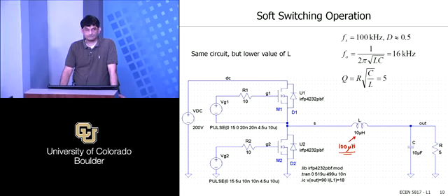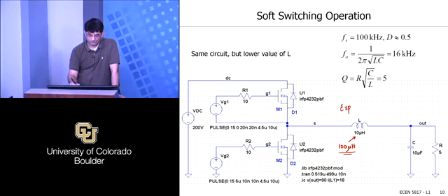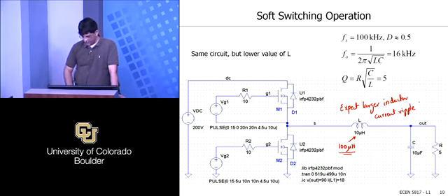Maybe it does not change much. Yeah, it's not going to change substantially. It may be slightly higher ripple, but the capacitor is still pretty large, right? So the big difference is that our inductor current ripple is going to be larger now. All right, so we expect larger inductor current ripple. So let's simulate this circuit and see what happens.